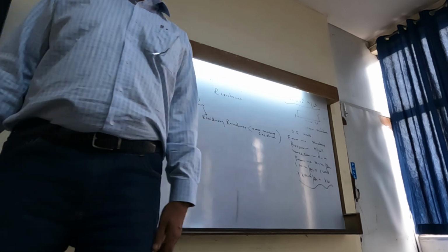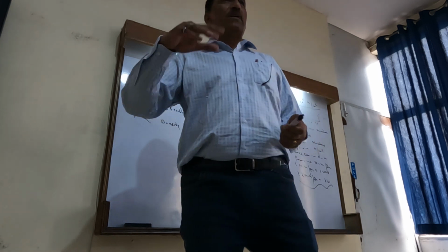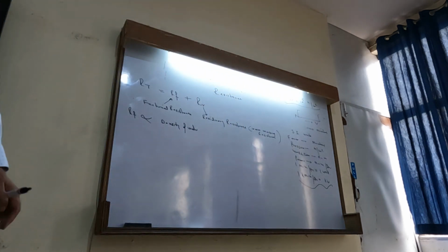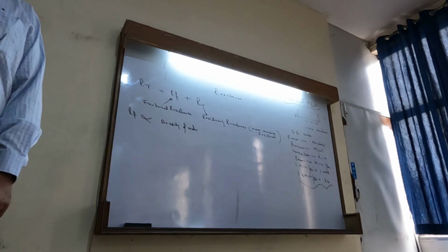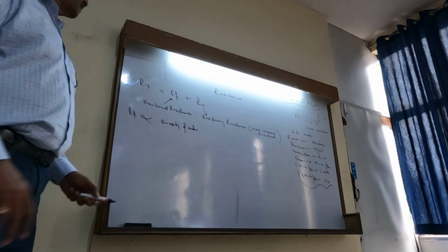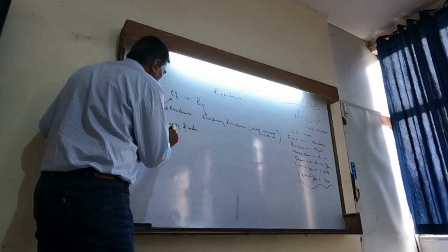We are taking 1.025 as the standard. Of course, it may vary from one place to another. So that means if I know the resistance in fresh water, if I multiply by 1.025, it will give me the resistance in salt water. It also depends upon the roughness of the hull.